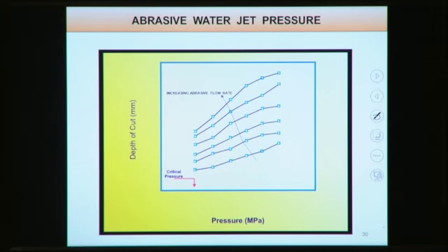Again, we can see here that with increasing pressure, depth of cut also increases. Increasing abrasive flow rate, you can see, if we increase the abrasive flow rate, in that case also the depth of cut increases.